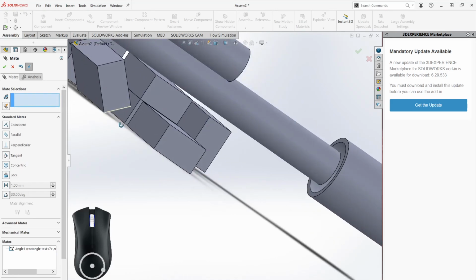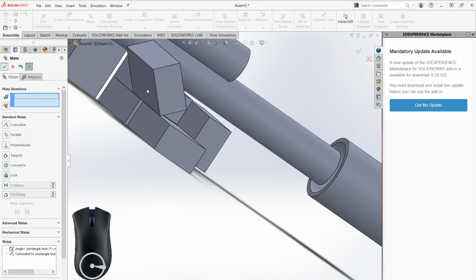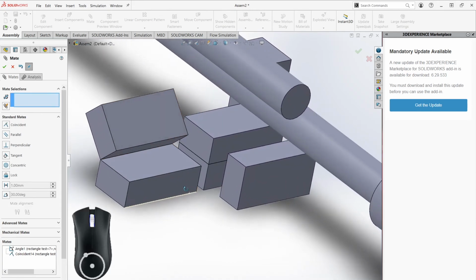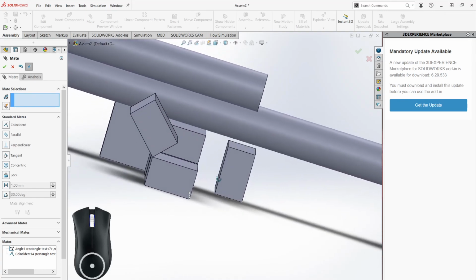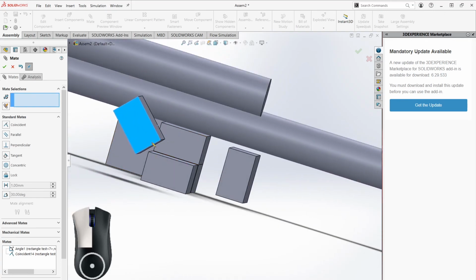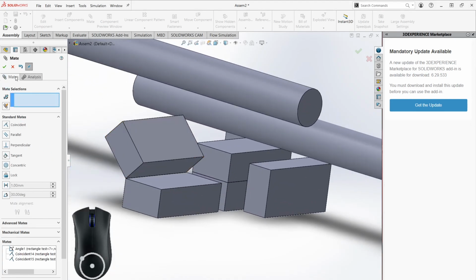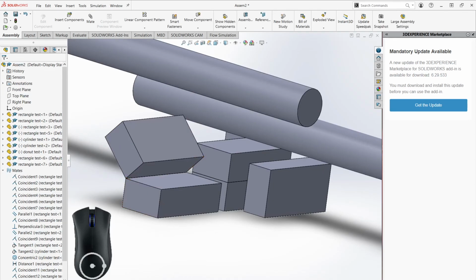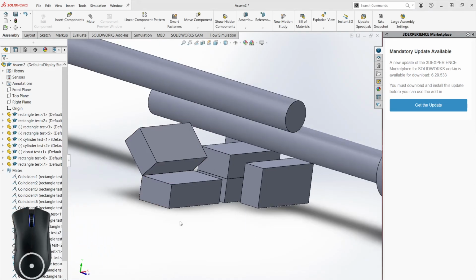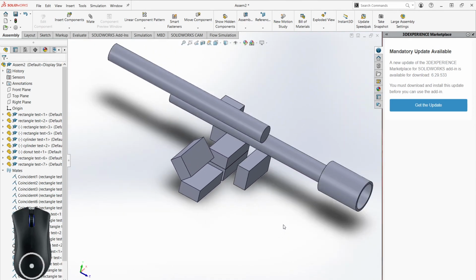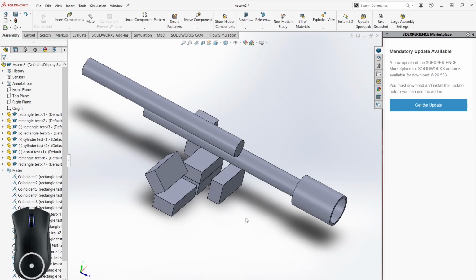So do that, and I can say that this is coincident, right? So coincident doesn't have to be just faces; it can be edges, points, or anything really. Now you can see that those two are 45 degrees apart. You could say maybe that mate coincident. And there you have it. Those are the basic mates that you'll see in SOLIDWORKS. Coincident will be your friend. Tangent and concentric are very helpful for mating screws or something into the right place.